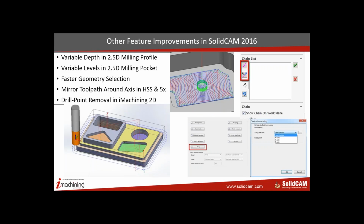Also, as I mentioned yesterday, just to remind you, for the people who weren't at yesterday's webinar, we have other enhancements and improvements within SolidCAM 2016 that include such things as variable depth on the profile, which allows you to select several profile operations of several different depths of cut, different face depths, in a single operation, thus saving time in programming.